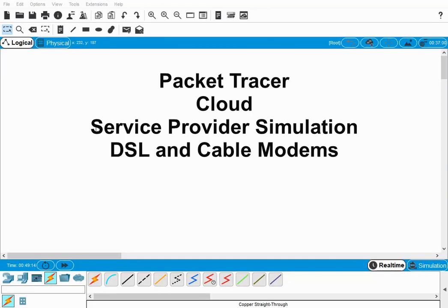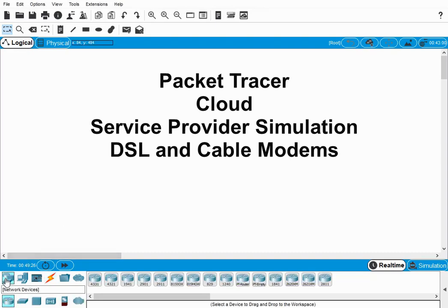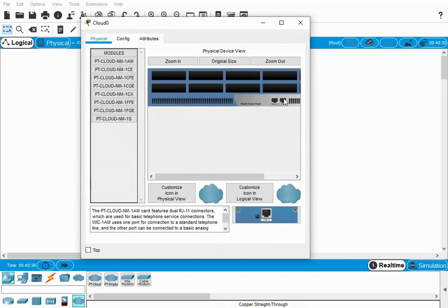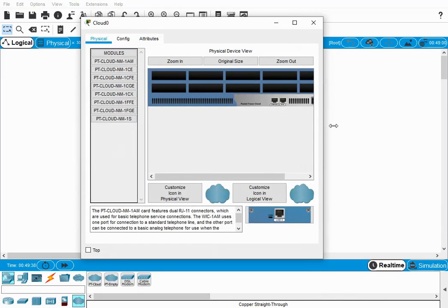Hi. This video is about using Packet Tracer to simulate service provider networks like TELUS, which is DSL, and Shaw, which is cable modems. So what we can do is go over here. The very first thing we want to do is set up our service provider. So we'll start with an empty cloud, right? We go to the empty cloud, and what we see is that we have slots here.